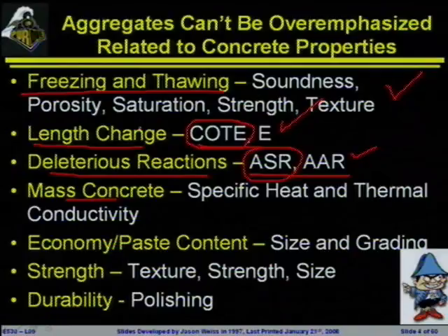They're either sitting there and holding heat, or they're transferring heat, or they are taking up space that the cement wouldn't normally be in. So if you took a cubic yard of cement, it's going to generate a lot more heat than a cubic yard of concrete, because there's more cement in the system reacting. So the aggregates can basically act to cut down the volume of the paste that's in the system reacting.